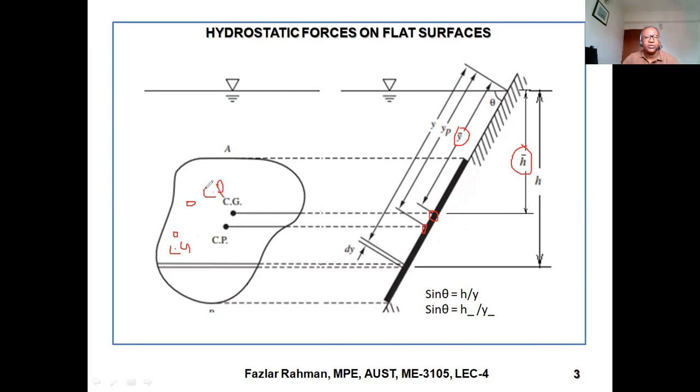You might have a question why we are not considering it like that. But actually, the center of pressure always works at the bottom of the center of gravity, and we can prove it mathematically. Okay, so right over here we are thinking of the center of pressure, and we indicate the distance yp. The vertical distance we don't need, but still you can figure it out, and you can say hp.